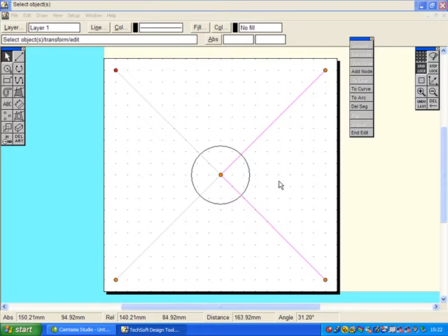In fact we have 8 lines doubled up on each other, and we can actually use those lines individually because we've got a node, 2 nodes to work from. Click on the outside, then click again on the line, and we're now going to change that line to a curve. Click on here to curve, and you see these little handles coming out.